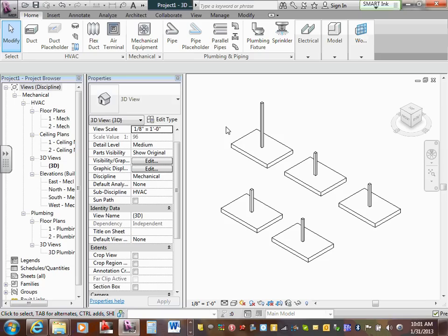So think about how it's being scheduled. Like you want all your A1. Are you talking about lights? Lights. So if I have the same fixture, 2 lamps or 3 lamps, if it's 2 lamps, we call it A1. If it's 3 lamps, say we call it A2, still the same. The way we did it in the program is we just grab the same family, edit type, and we give it a new name, and we start dropping the 2 types that we edited. So duplicate it.